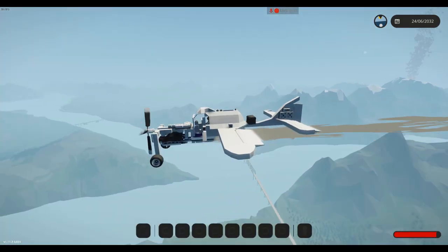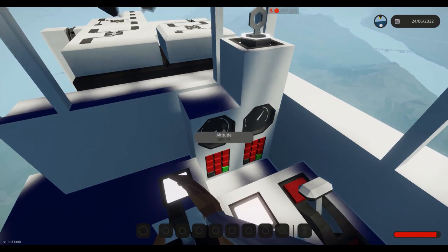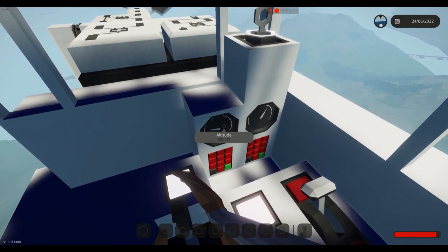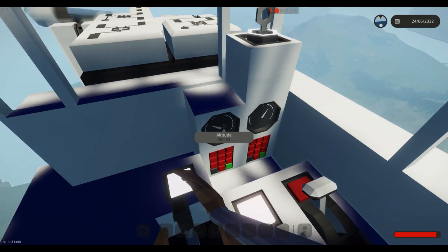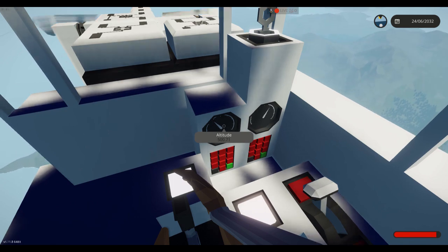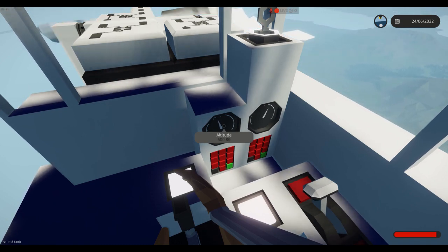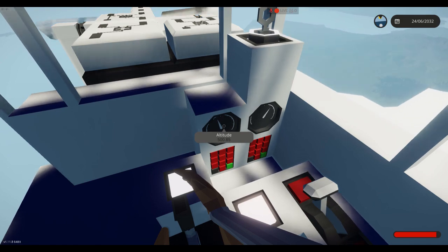And I believe the function block is still there. So yeah, now the function block where it subtracts 5 is also going to be working hard. So as you can see, we've just hit 500 and it's staying nice and stable. We're not at 501 yet. We're not at 502. We're not at 503. We're just at 500. Well, 500.80, but within 1. If you can get your system within about 2, that's a good system.